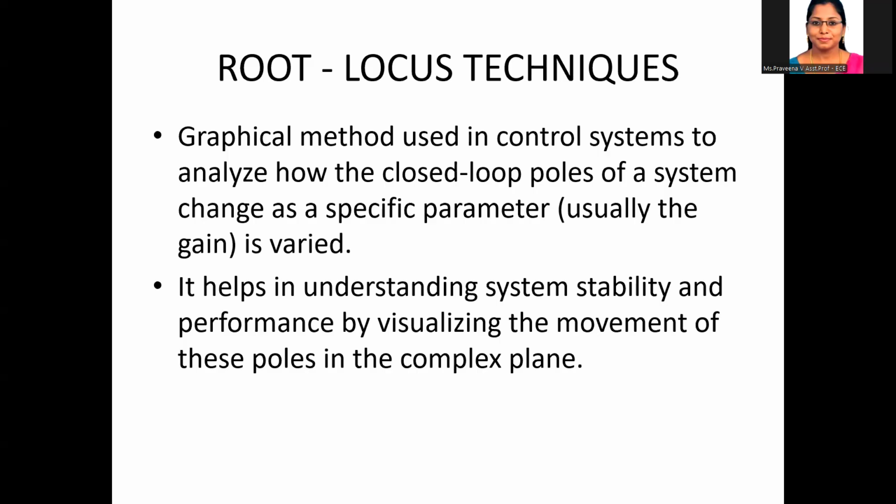Generally, what is the purpose of root locus? It determines your system stability, and it also shows how the gain changes based on the pole location. It also helps in designing the controller and analyzing the performance of the system. The advantage is that it is a simple graphical technique, and it provides information about stability and transient response. That is the main advantage of the root locus technique.